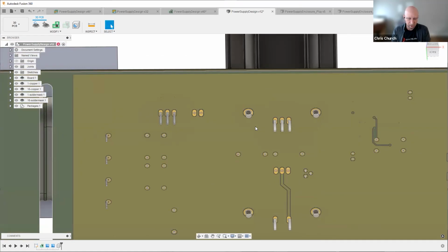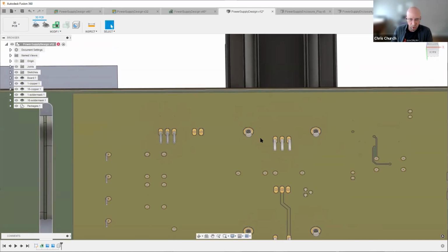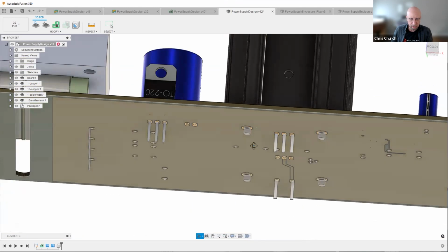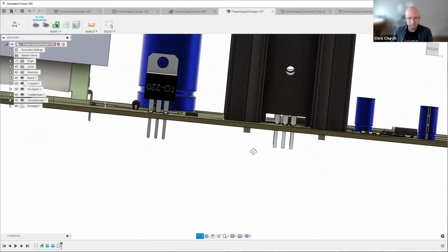But typically, if we look at these heat sinks, they're going to have a hole in them, and those holes are going to be threaded. And we'll see that right here, for example, there's that threaded hole. We're going to use those because they're threaded. They line up with that hole in that TO220, and that's going to enable us to put a screw in there. And from the manufacturing perspective, we still need to transfer heat from that TO220 to the heat sink.